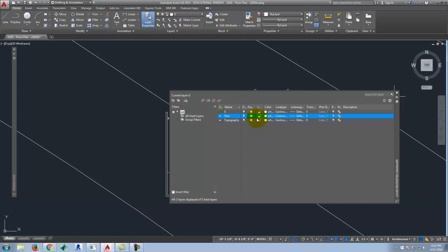The truth is that a line drawing really isn't very hard on a computer anymore. We've got plenty of power to deal with them, but it is there, and there is a difference. If I were to have you start to learn something, I would turn on and off layers by freezing and thawing them. If you get in that habit, you're always going to be better off in the long run.